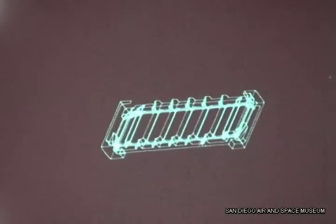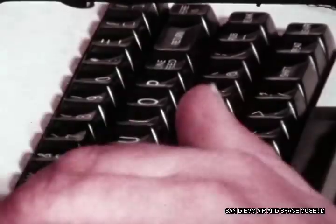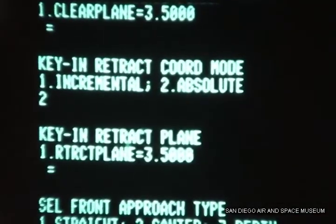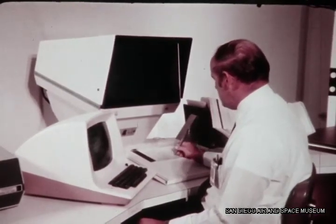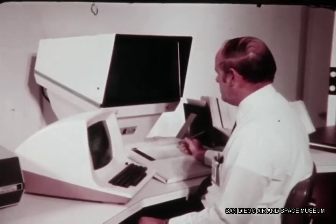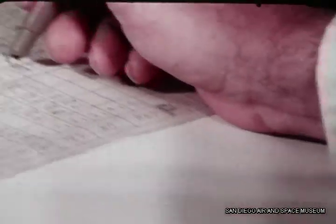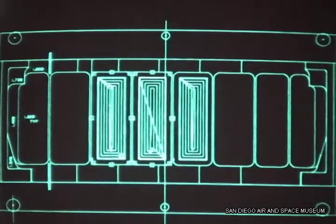The structural plate has been designed and the data stored in the computer. Now the machine tool has to be programmed with specific operating instructions, which is done at programming terminals at Lindbergh Field. The part programmer accesses the system and calls up the configuration created by the design engineer. Using symbols from his menu and an electronic pen, he inputs to the computer the desired machine tool cutter path and other pertinent tooling information.